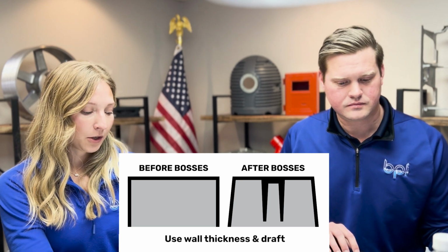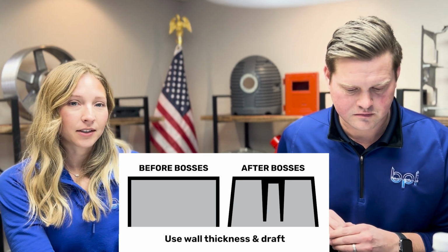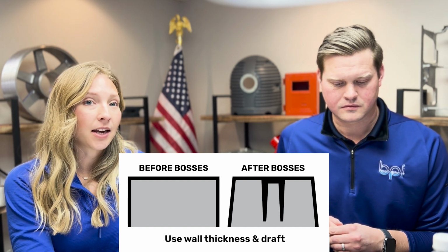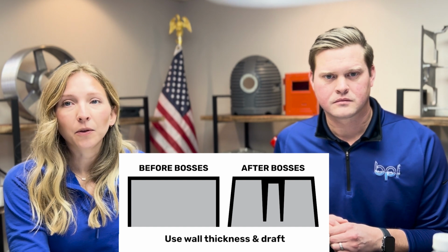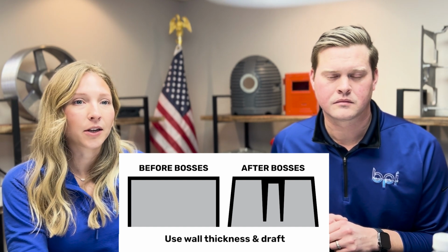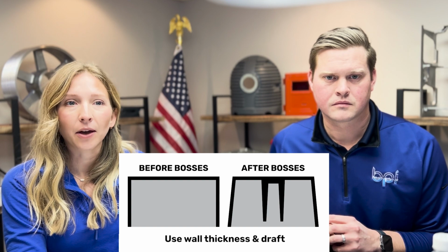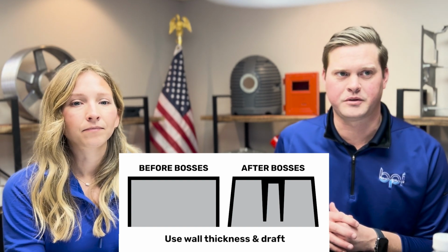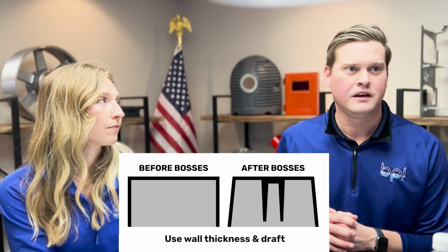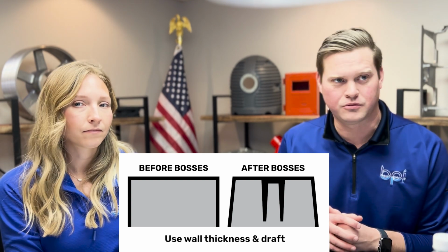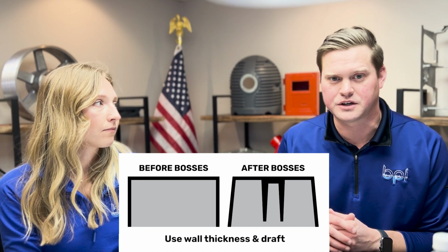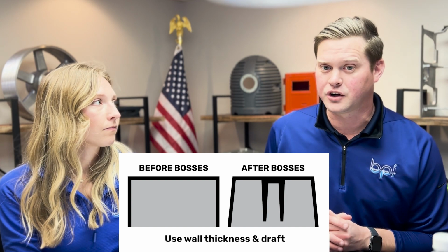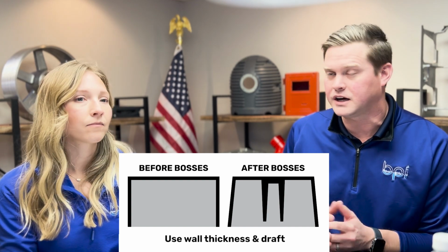Bosses. So you don't always need these, but when you're designing these, it's good to remember just maintaining uniform wall thickness helps with bosses, as well as including draft and fillets to help these fill out correctly. Yeah, absolutely, and it's definitely something we see a lot in our process. But if you don't design it right, you run into issues. And then, again, Rachel mentioned earlier, but the end goal in mind here is to make sure that we're providing a good design, a good casting up front before even cutting the die.